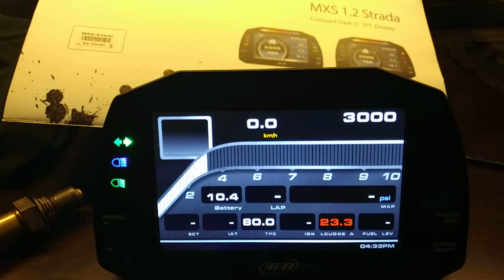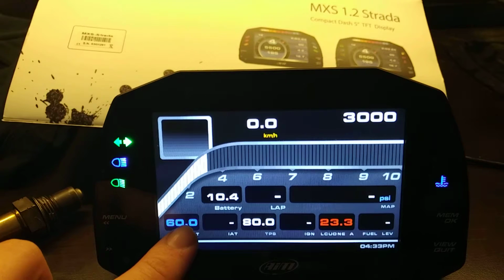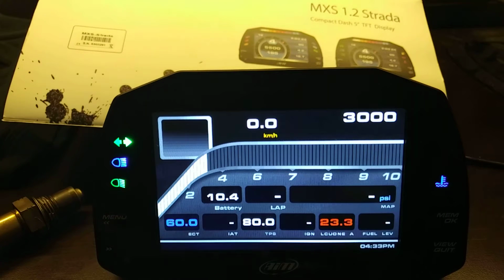So we can go through and step through the rest of the alarms here. Let's say the coolant temperature: if we have 60 degrees Fahrenheit of coolant temperature, that value will show up here and it will be shown as blue, as well as the value over here on the icon, to signify that the coolant temperature is still cold. So let's say if we step to 215, which would be above a certain alarm, the first stage of warning, it'll indicate yellow. And then if we go to, let's say 235, it will show a coolant temp warning. So we'll go back to 215.